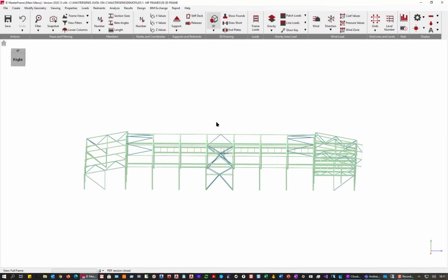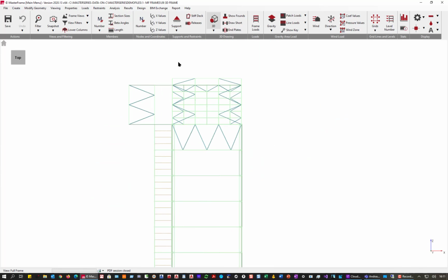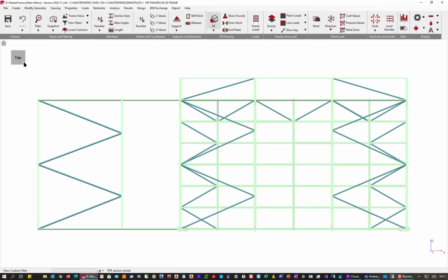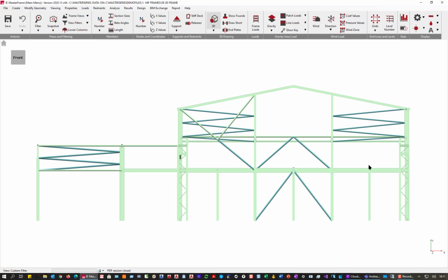So for example, if I was wanting to do the first floor in this area, I would first of all say, right, let's put it in top view. There we go, and it's this area here. So I would come along and I would just move the mouse to the bottom of that and filter. And now I would push it into, say, front view, and now I can zoom in on this level. So like a cake, you're cutting it in at different orientations to divide it up.